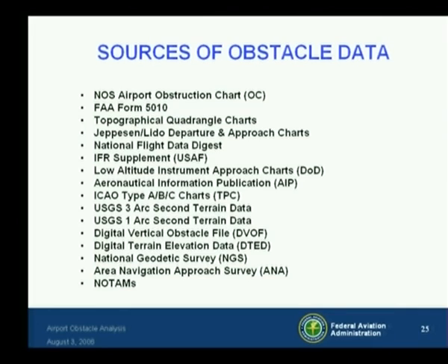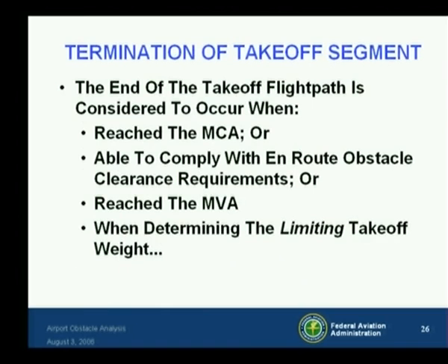Of primary importance in the engine-out procedure analysis is determining the end of the takeoff segment. For the purpose of the takeoff obstacle clearance analysis, the end of the takeoff flight path is considered to occur when one of these things happen.